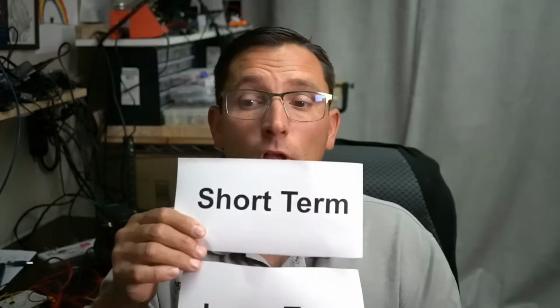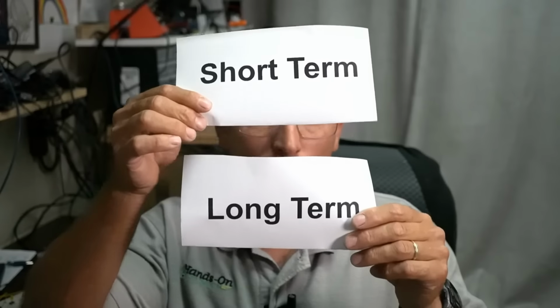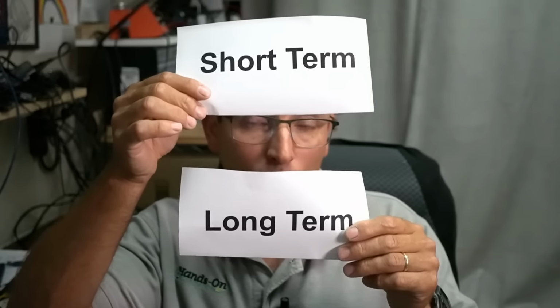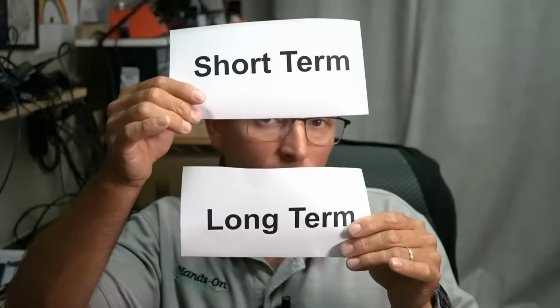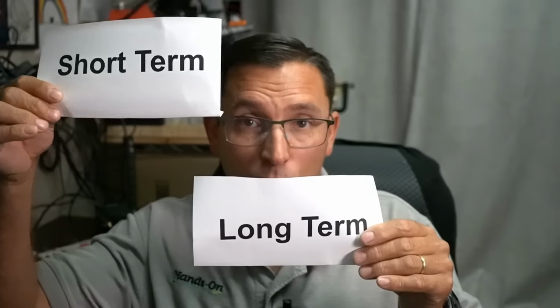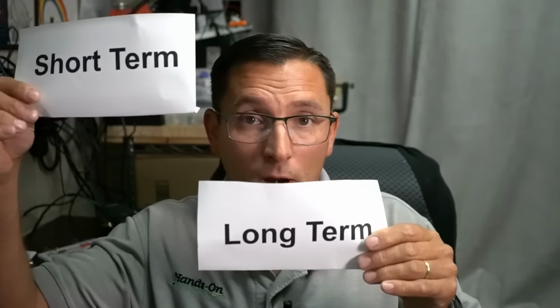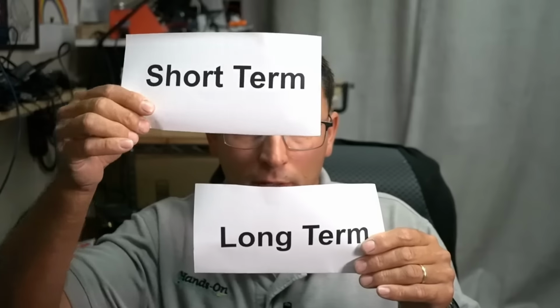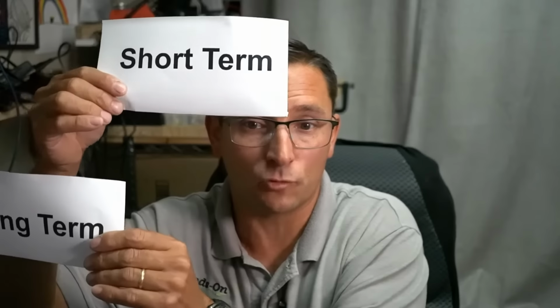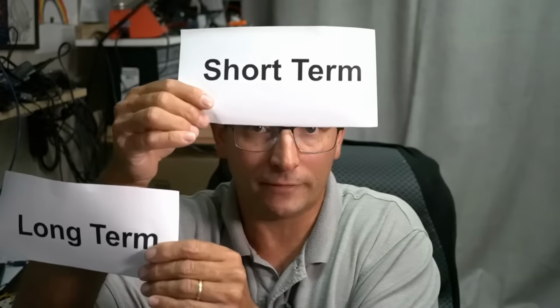So we start the vehicle up on a good running day. Short term and long term will be right here, right next to each other. And if we're running one way, I don't care, let's just not use any positive or negative. Let's just say short term has to go this way to maintain the proper operation of the vehicle. So short term kind of goes over here and it starts hovering over here. And long term is going to go over and catch up. As long term goes to catch up, the short term will come back to 0.